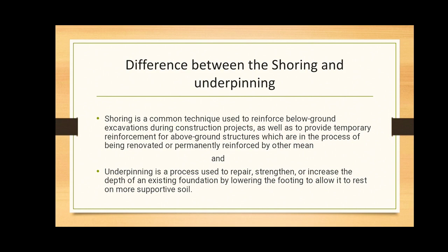Shoring is temporary support to a structure where the foundation is repaired or the adjacent building is to be repaired or rebuilt, while underpinning is the method of providing support to the structure by providing a new foundation or a permanent structure for another existing building. This is the underpinning. Shoring is a common technique used to reinforce below ground excavations during construction projects, as well as to provide temporary reinforcement for above ground structures which are in the process of being removed or permanently reinforced by other means.